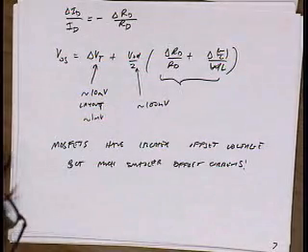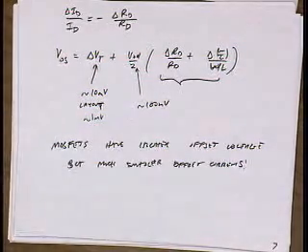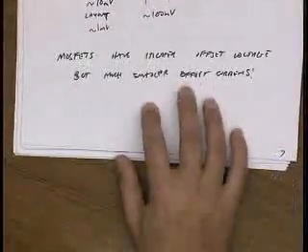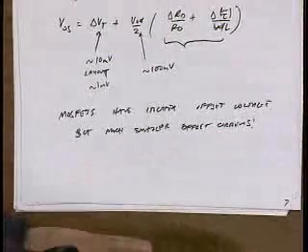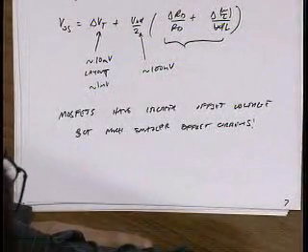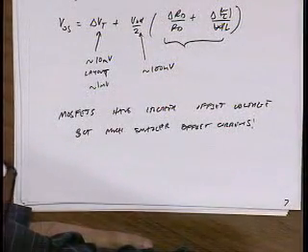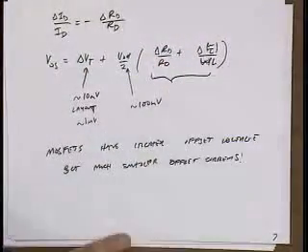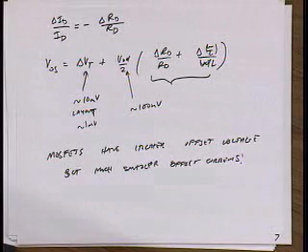Now, one thing to point out here is that we're going to use the term random in different ways in this class. We call this the random offset, and the reason we call it a random offset is because it exists because of these delta terms. If deltas were 0, if the circuit were perfectly symmetric, the offset voltage would be equal to 0.